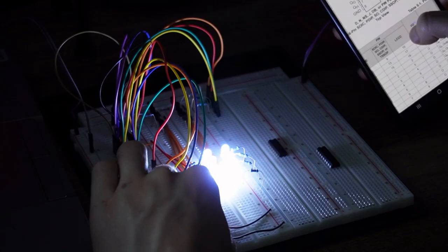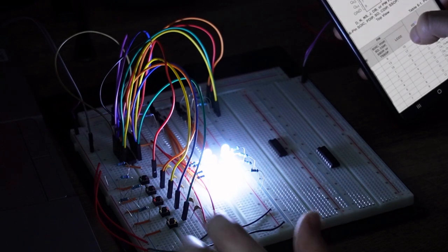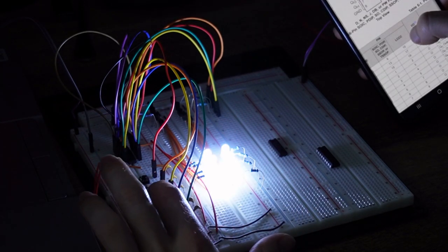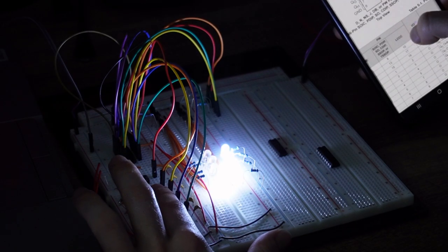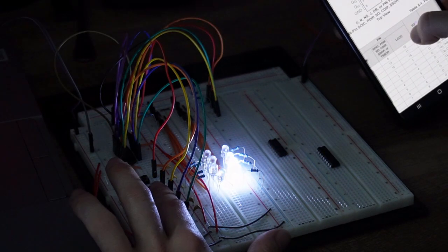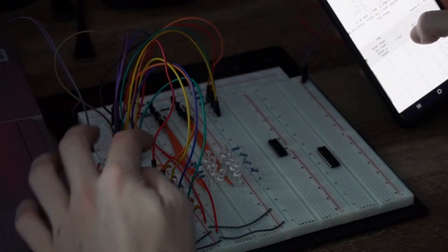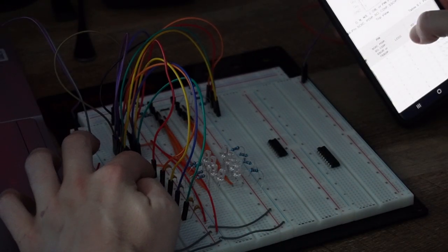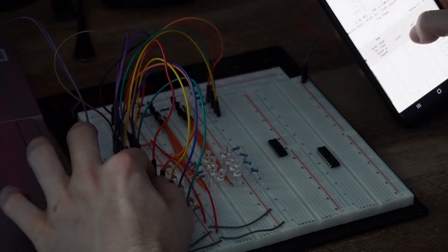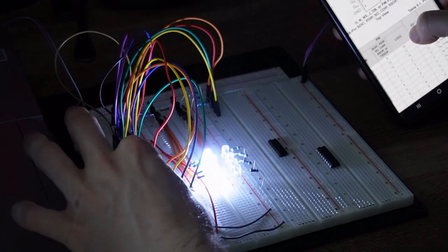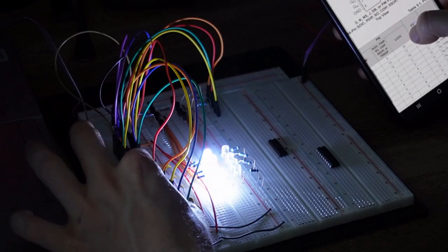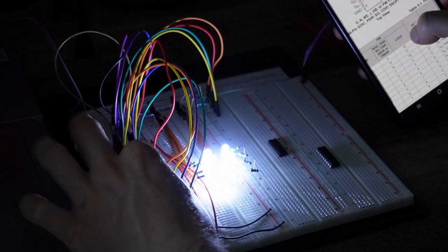So I'm going to set them all high now. And then I'm going to just shift in back a bunch of zeros. Okay, now I'll go ahead and hold the serial button high, send a clock signal in, and then send it to the output. And if I just repeatedly do this, we'll see that I actually keep shifting in a new value, so the whole array starts lighting up one at a time.